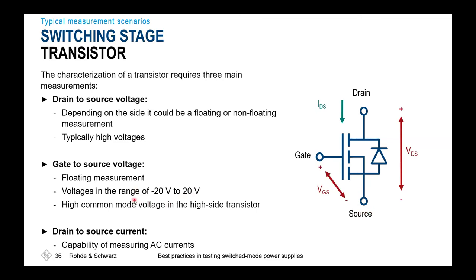On top of that, when investigating silicon carbide, gallium nitride gate drivers, typically these are floating too. So it's always depending on how high their isolation impedance against the environment and the ground itself is. And in dependency of this relation between the gate isolation and the isolation provided by the differential probe, you'll see more or less effects.